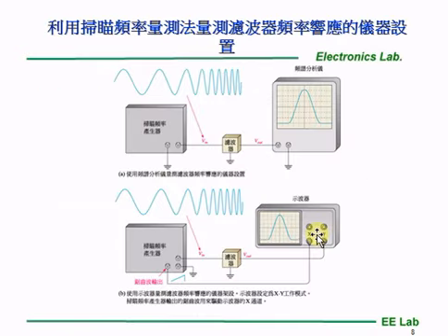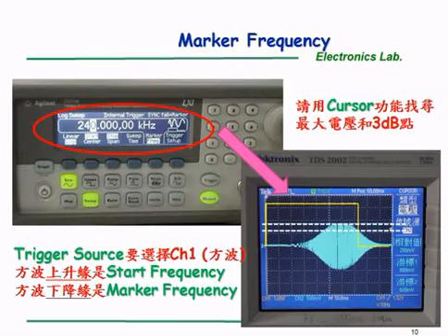The concept behind the second part of the experiment is that we use the function generator to generate a signal whose frequency changes through time. Therefore, we could observe the changes on the oscilloscope, which records the amplitude of the signal through time. However, you cannot easily derive the frequency from the time observed. This is the reason behind the marker option of the function generator.